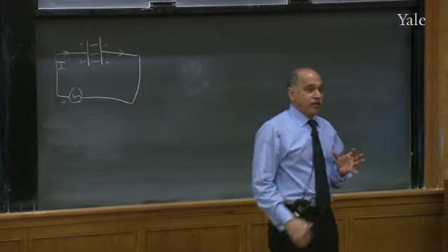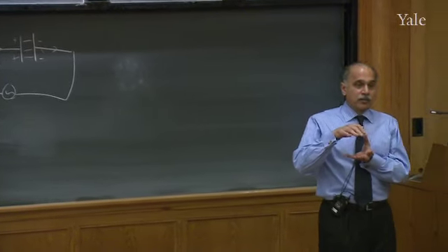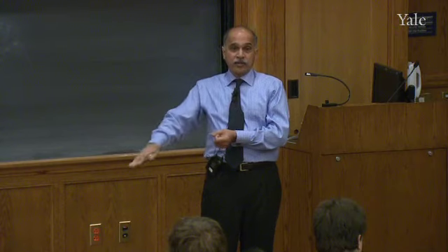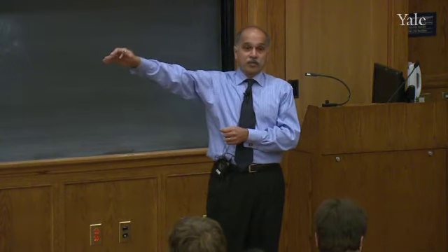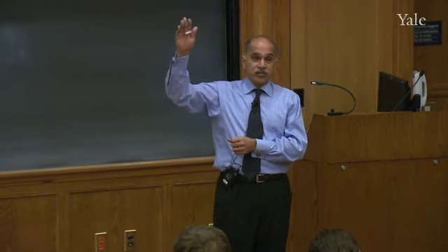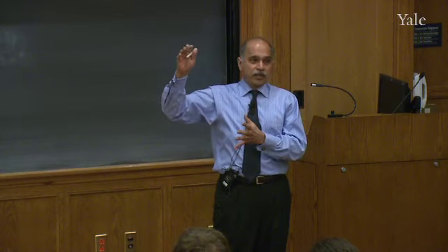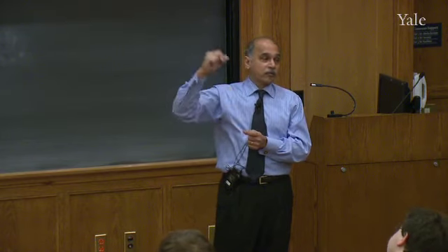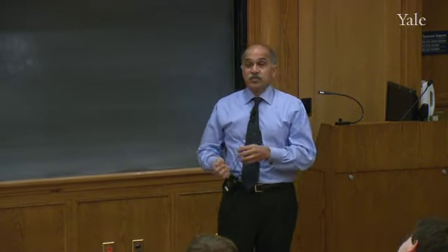That's like a lightning strike inside the little world. That's what happens to us during a lightning. We are in a capacitor. The lower plate is the earth, upper plate is the clouds, and after a while there's a heavy charging. At some point they cannot take it anymore, and they ionize the air, and they create a little path, and the current flows through that, and the clouds are discharged.